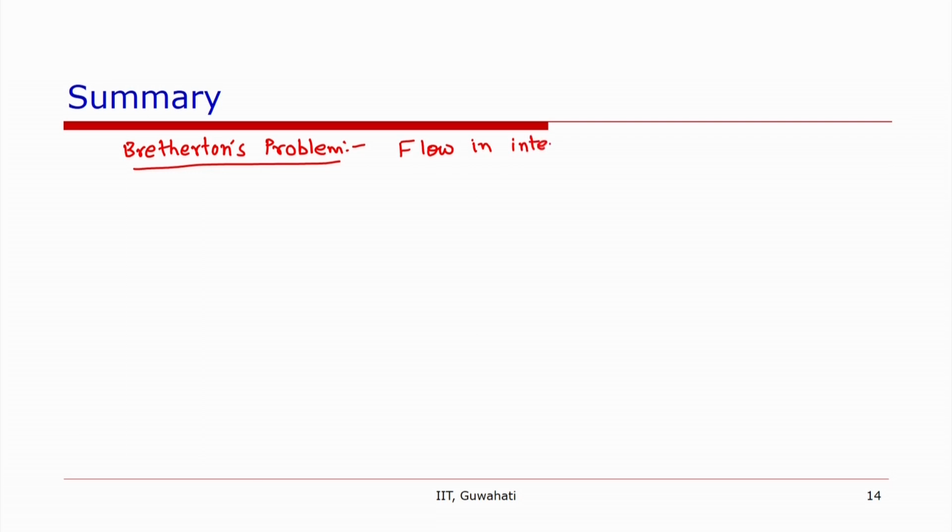First we divided it into 3 regions, where in the other 2 regions, near the front and in the constant thickness film cylindrical region, we had some information about the flow. The film was stagnant. So we looked at flow in the intermediate region, used the lubrication approximation, and obtained the expression for Vx.